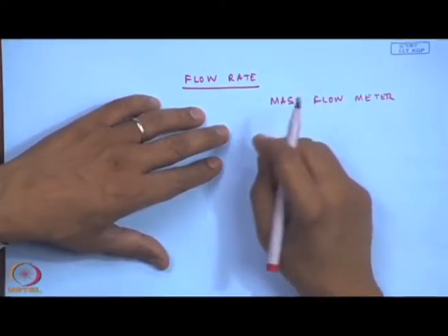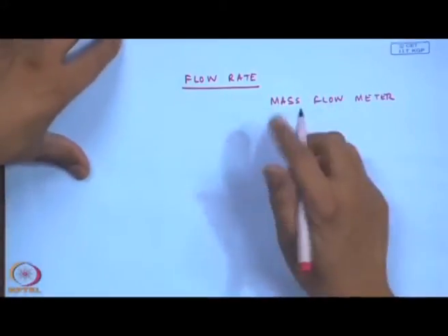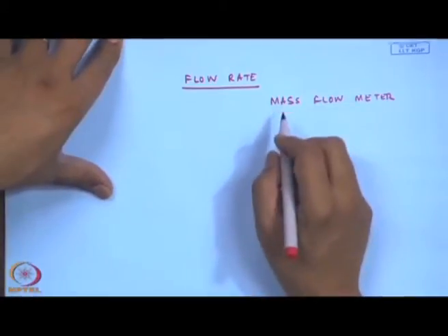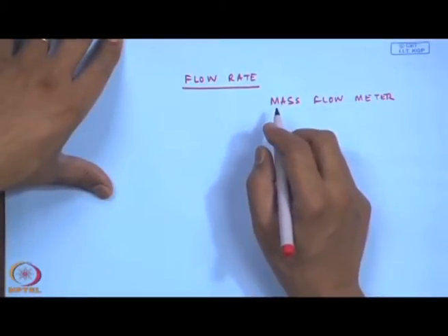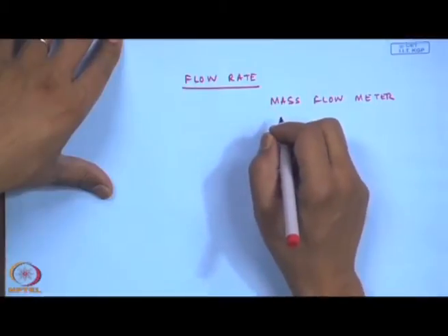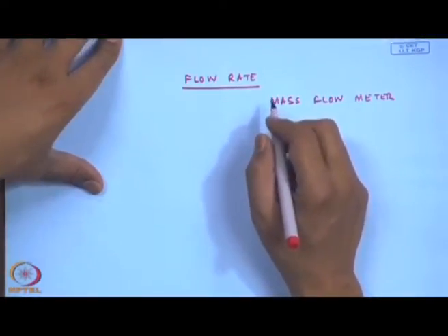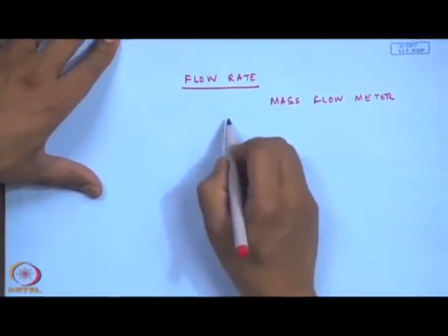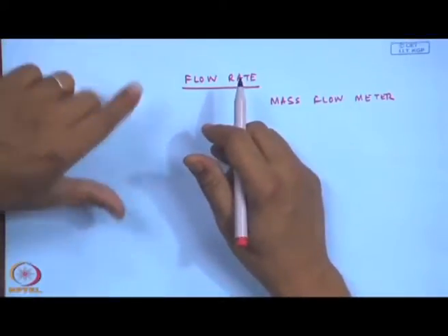And many times, because these compressors increase the pressure, there is also an increase in the temperature, okay. And particularly bearings, because some effect of the compressor's operation is going to affect the auxiliary devices, particularly if the compressor is defective, the bearings may go bad.